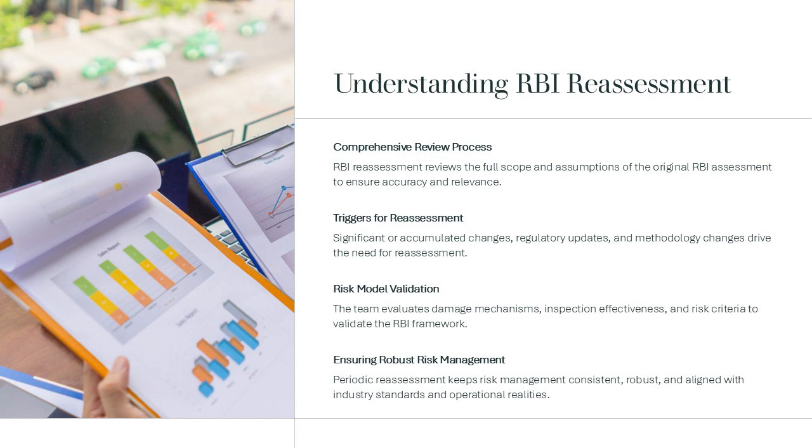Reassessments are performed at longer intervals and are often driven by significant changes or accumulated minor changes that collectively affect risk. During a reassessment, the team reviews damage mechanisms, inspection effectiveness, consequence models, and risk criteria to confirm that the RBI assessment remains appropriate and defensible.